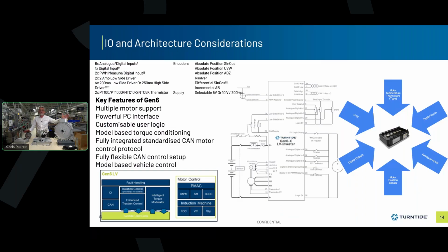for different drivability profiles. We can then start thinking about setting up economy modes to limit ramp rates of torque, maximum speed, and reduce DC link current consumption, which all go towards increasing range, or implement interlocks, immobilizer functions, or any kind of user function that is bespoke and unique to your application. That's available via user code.